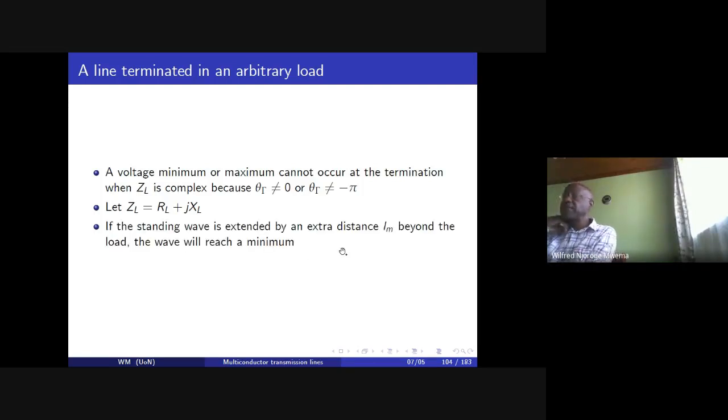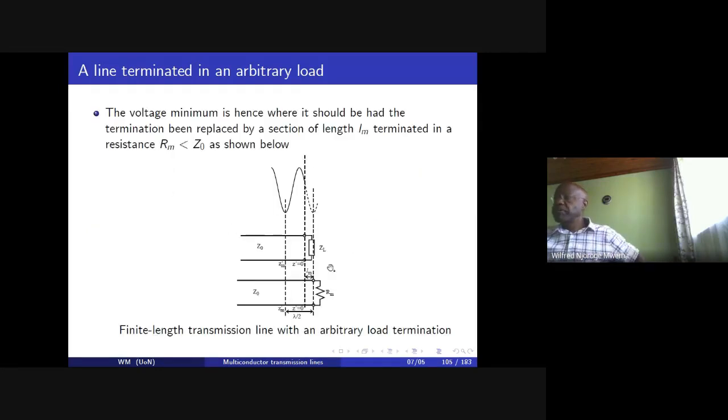So if we were to extend the standing wave beyond the load termination a further distance Lm, it's possible for us to reach either a minimum or a maximum of the voltage standing wave amplitude. This is what we have expressed here.